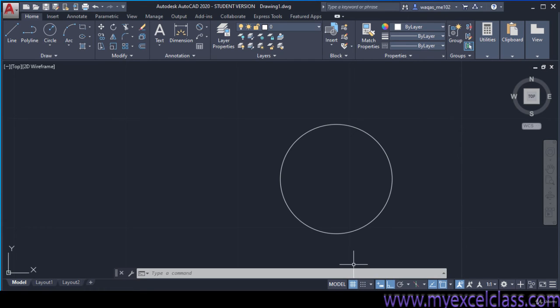So next, here are some basic command bar options: create snap, ortho, which means you want all drawing at a specific angle, that's 90. You can choose here. Here are the different angles. When I have selected this one and click again, now it is unselected. When I click here, now it has been selected.